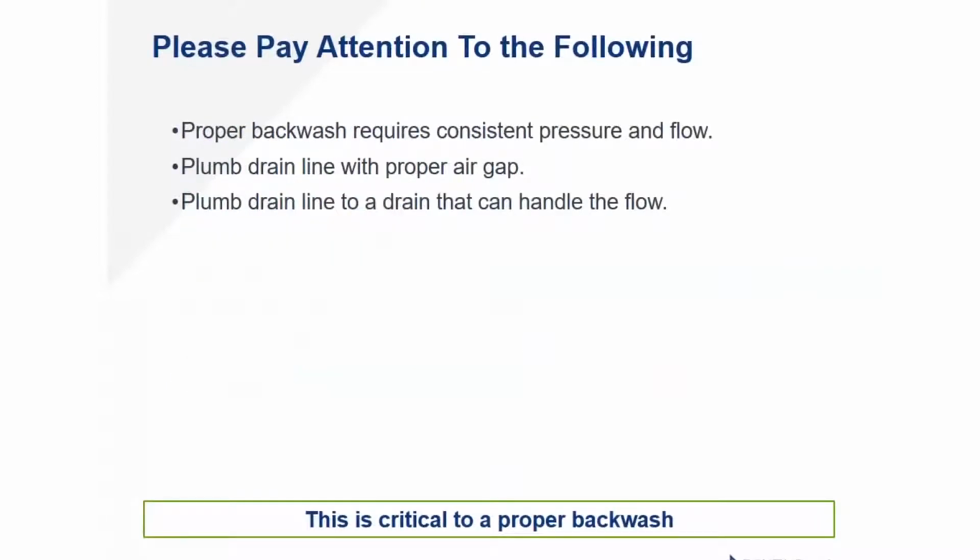So during an install, pay close attention to the following things. Proper backwash requires consistent flow and pressure. So if we have an undersized well tank or an improperly pressurized well bladder tank in a residence, this will impact consistent flow and pressure, impacting the quality of backwash.